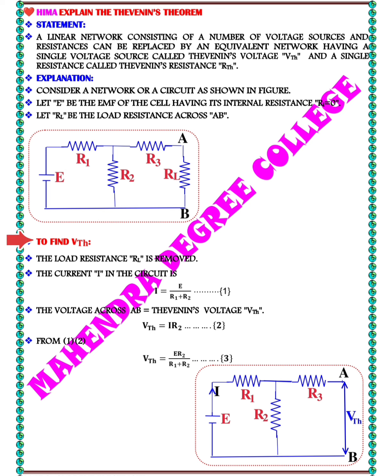Next, we find the value of Thevenin's voltage, VTH or V_TH. The load resistance RL is removed. Simply, the load resistance is disconnected from the terminals A and B. Already, we know load resistance refers to the opposition that a load offers to the flow of electric current in a circuit.